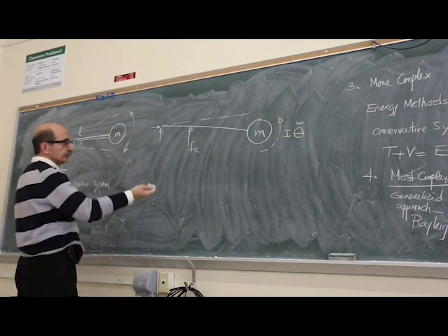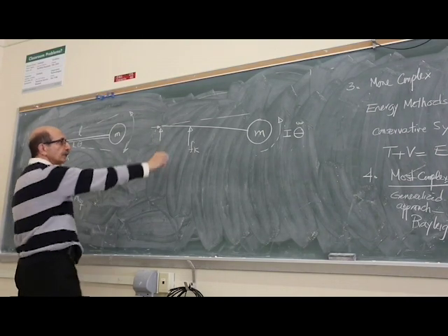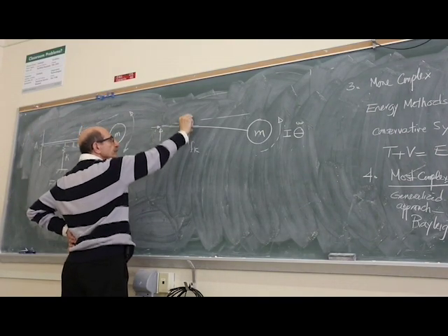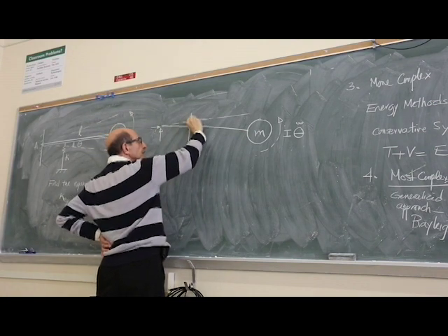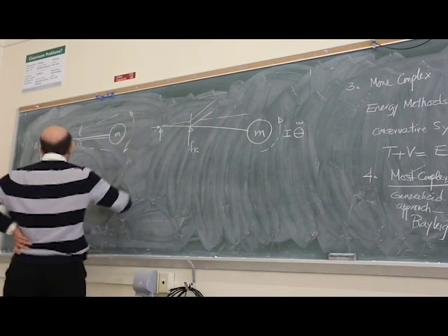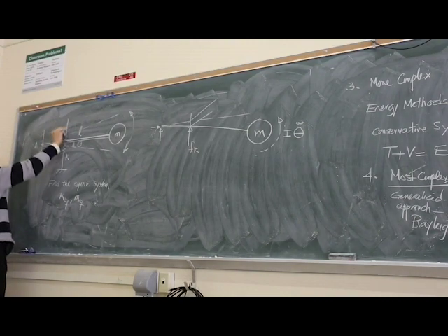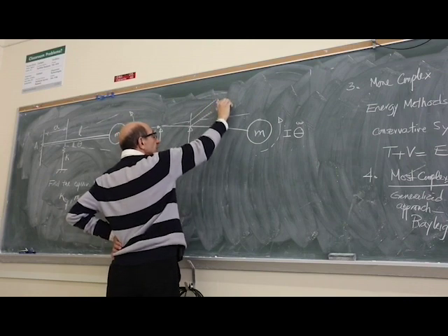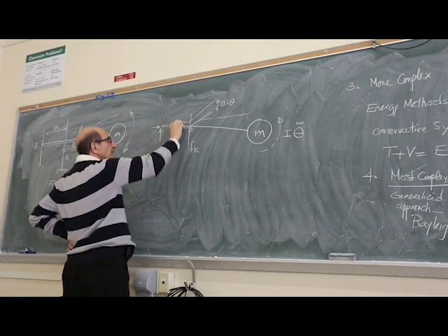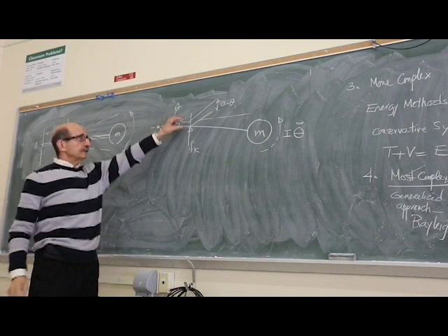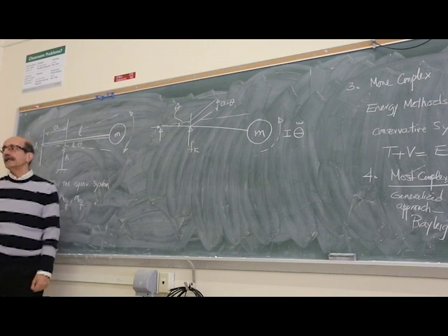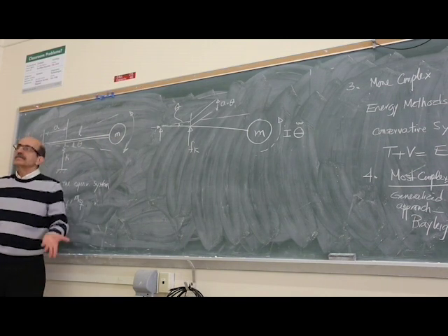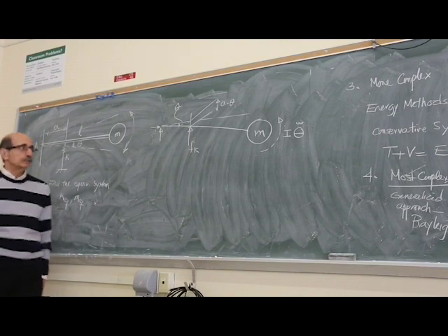So let's just set up the equations of equilibrium. This spring is going through a deformation. If this is, let's say, A, it is experiencing a displacement, which I call A times theta. If this is a small angle, that displacement would be A times theta. It's actually A sine theta, but since theta is very, very small, sine and the angle would be equal.